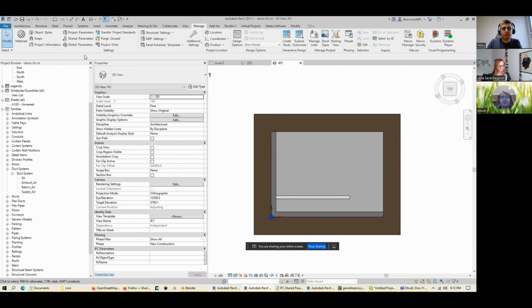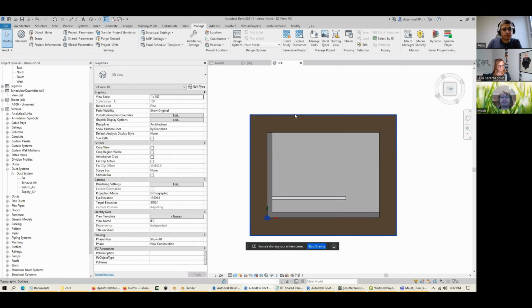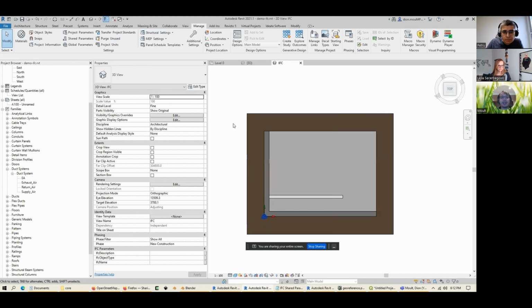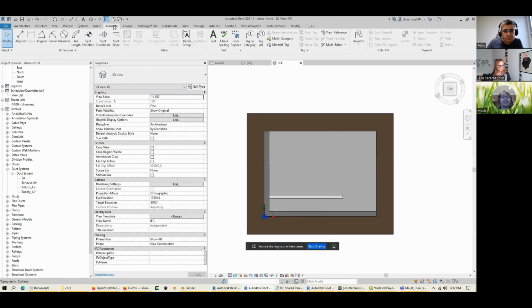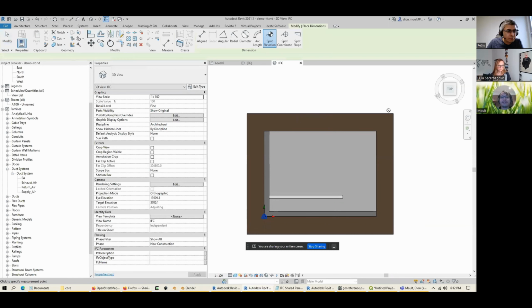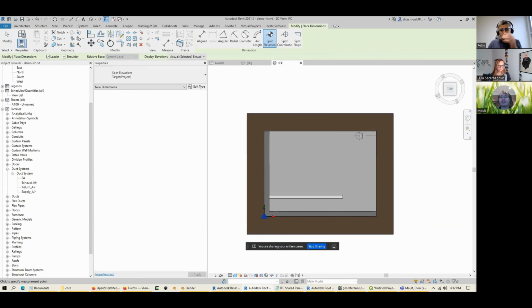And so that's another thing I want to highlight, because Revit does not support the concept of a combined scale factor, that if your project uses this combined scale factor and you're an architect working in local engineering coordinates, if you use this tool, you will actually get incorrect numbers. Sorry, I'm using the wrong tool. So you cannot trust these numbers.